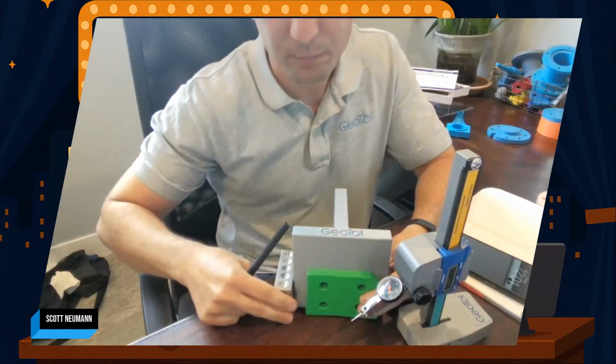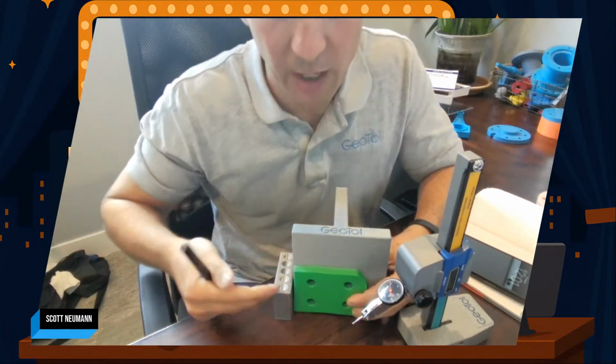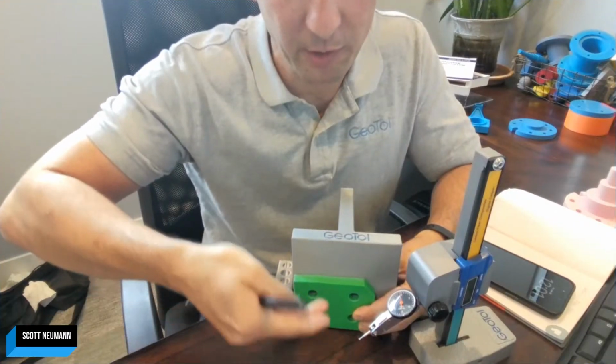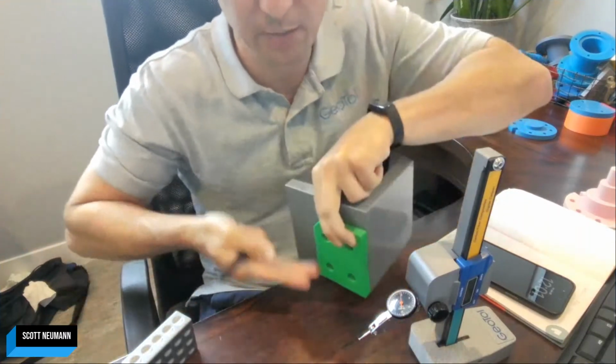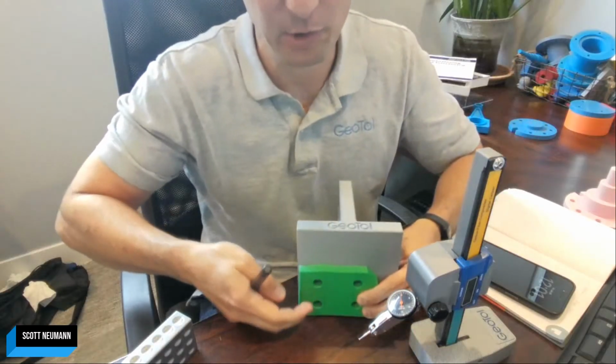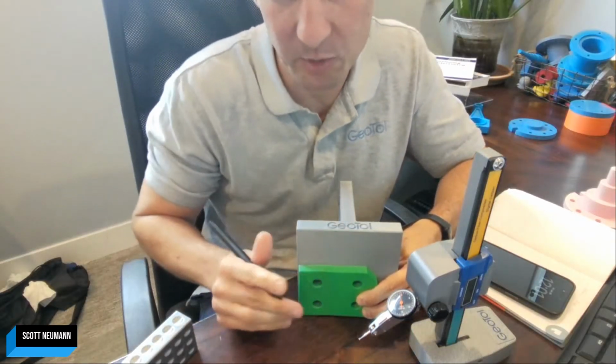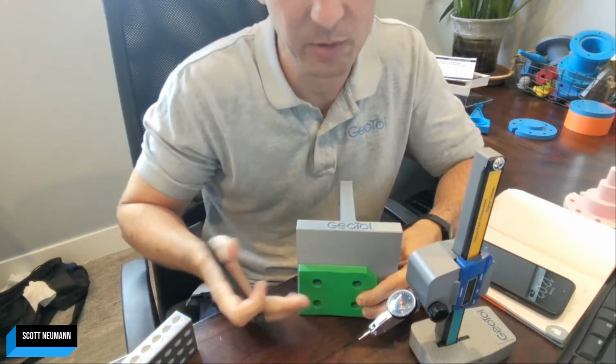Oh, you wouldn't need a CMM for something like this. This is such a simple geometry. This would be very easy, angle plate with a basic height gauge. So you'd set up the angle plate, set up A, set up B. You have probably a gauge block over here for setting up your C, and then measure the hole in the Y direction, rotate, measure in the X direction, and then make sure that combination of X, Y, like Custis was saying earlier with the Pythagorean theorem, still lies within that tolerance zone.